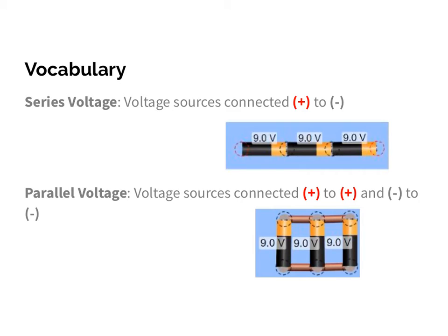Okay, so let's say I wanted to increase the voltage of a battery. One thing you guys had to practice with was aligning batteries in different ways. There are 2 ways you can align batteries. One is called a series and one is called parallel. Series is when you line the batteries up from positive to negative. Okay, so understand when you see these, the left end would be negative, positive, and then notice I got negative, positive, and then negative, positive.